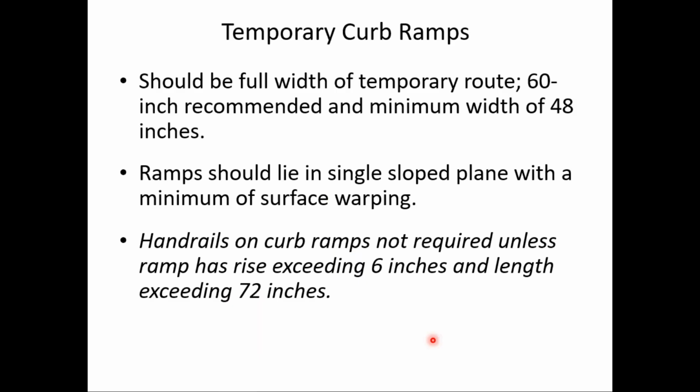The ramps need to lie in a single sloped plane. There should be a minimum of warping of that surface. And of course, normally with curb ramps, we don't worry about railings, but ADA says handrails on curb ramps are not required unless the ramp has a rise exceeding 6 inches and a length exceeding 72 inches. So something to keep in mind.